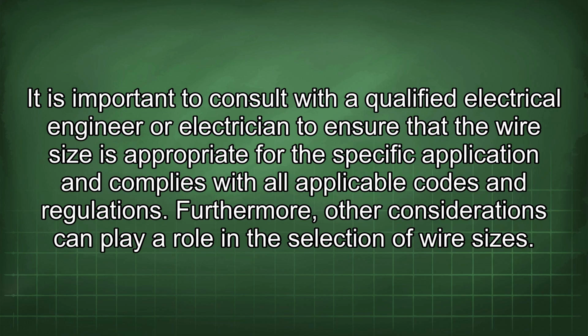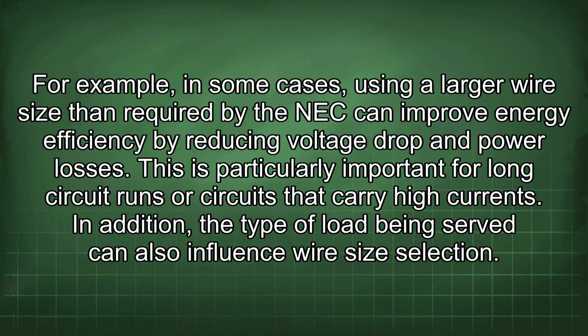Furthermore, other considerations can play a role in the selection of wire sizes. For example, in some cases, using a larger wire size than required by the NEC can improve energy efficiency by reducing voltage drop and power losses. This is particularly important for long circuit runs or circuits that carry high currents.